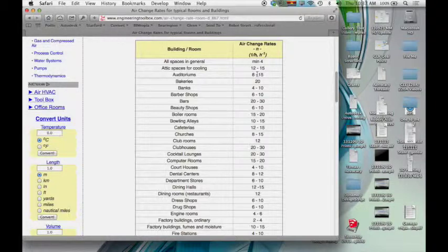That's a problem with a lot of very tight construction, especially today as we try to build houses with next to zero energy consumption. We still need to move the air, and maybe move it in such a way that we aren't bringing in a lot of cold from the outside. We have to do all sorts of heat exchanging to keep the air at a relatively constant temperature. But the ventilation is absolutely required.